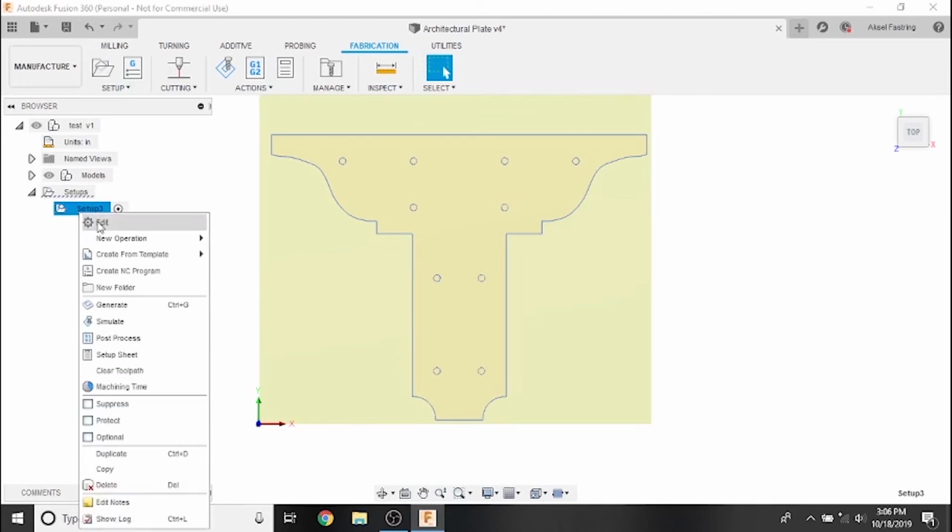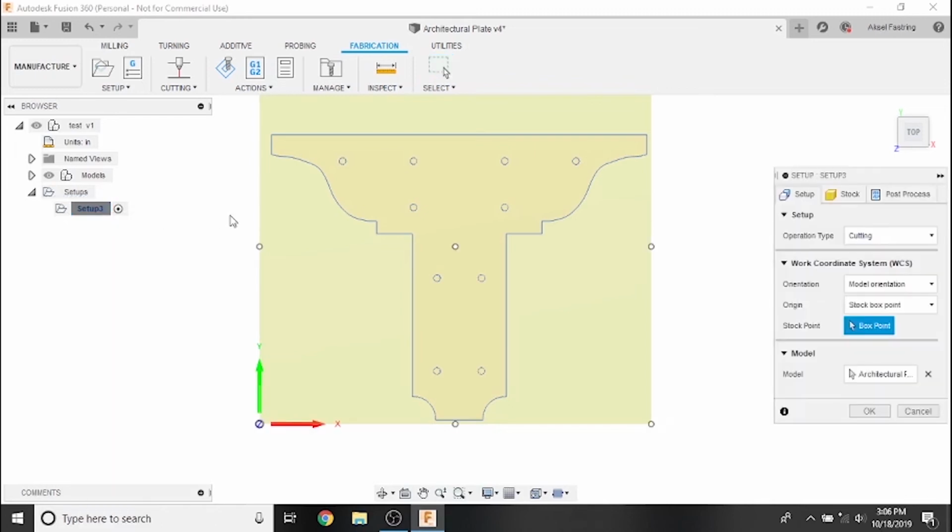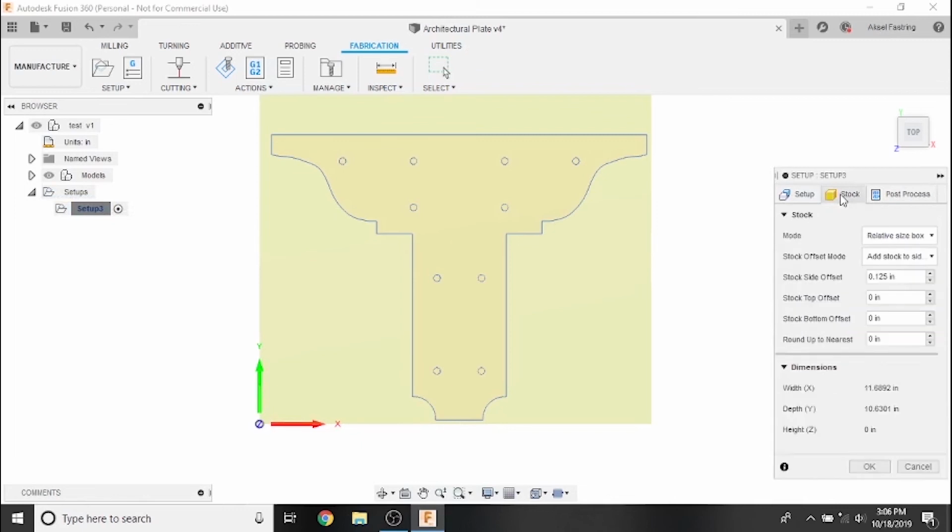Picking up where we left off, since the Crossfire has no Z-axis control, we'll leave the top and bottom offsets set to 0. If you're using a Crossfire Pro, we'll cover Z-axis control later. This bottom portion of the Stock tab simply shows us the overall area our part's stock outline takes up.